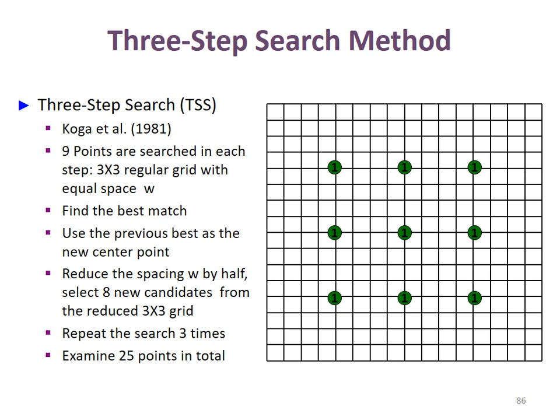And then we define 8 different neighbor positions, which are 4 pixels away. Okay. So in this case, we can calculate the mean square error of these 9 positions compared to the current block in the current frame. Okay, and then we can choose the smallest one. Once we choose the pink position, next we shrink the distance of the neighboring pixels by half.